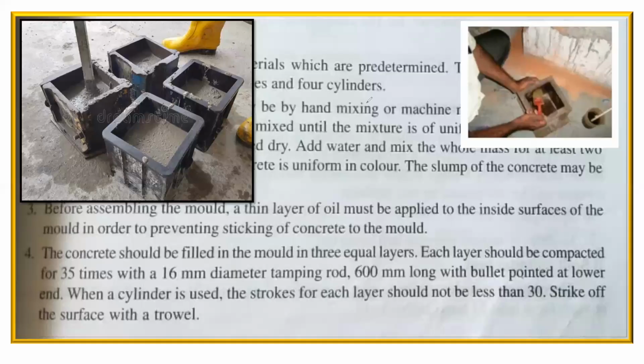So what it's trying to tell is, when you fill the concrete in the cube, you have to fill it in layers, right? So how do you decide that? If you refer to the Indian Standard Code books, it says that you have to fill 5 centimeter at a single time, right? I'll write it here: 5 centimeter will be each layer.